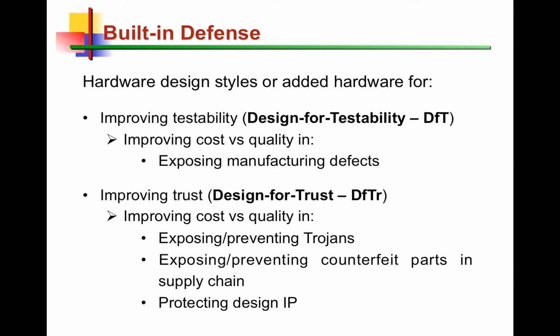There is also the concept of defense. In the testing domain, to test every single chip, of course, we spend time on expensive testers, so there's a cost associated with it. It's a recurring cost. And there's the quality, of course. If we spend more time, we can test it better, so we get fewer test escapes or higher fault coverages that define quality. So there is this cost versus quality trade-off in the context of testing.